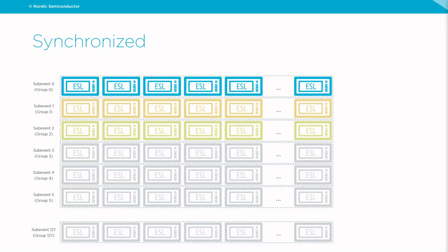When you have tags in synchronized state, they can receive commands and send responses back over PAwR. You can start doing so as soon as you have at least one tag synchronized to the access point. Indeed, the procedure to associate tags can be done at any time while the access point is up and running and operational, while sending commands and receiving responses over PAwR.